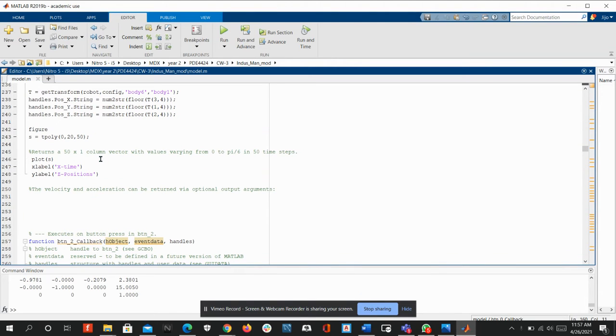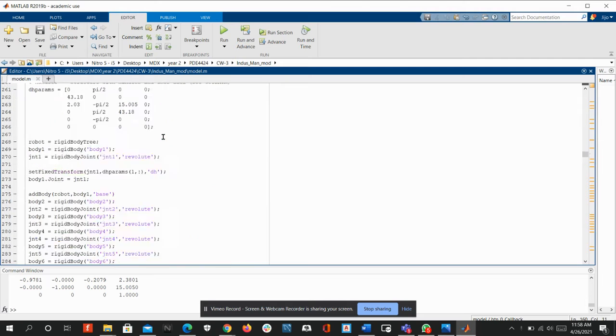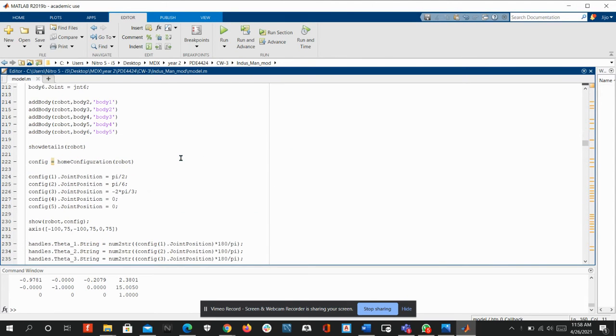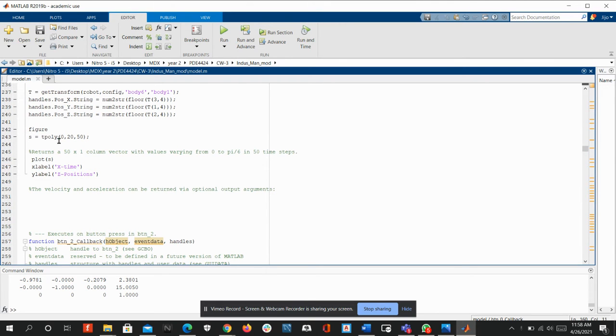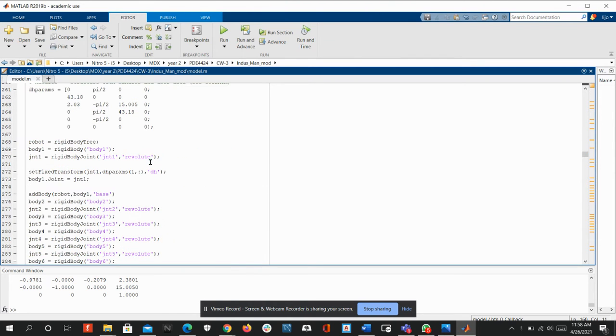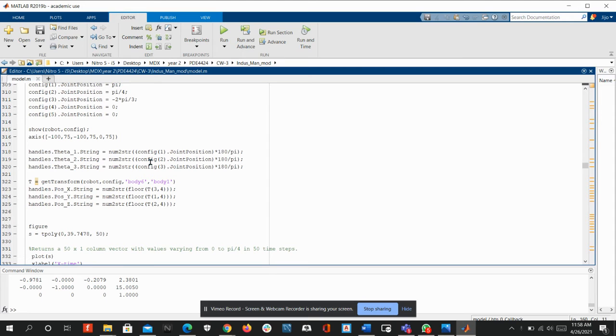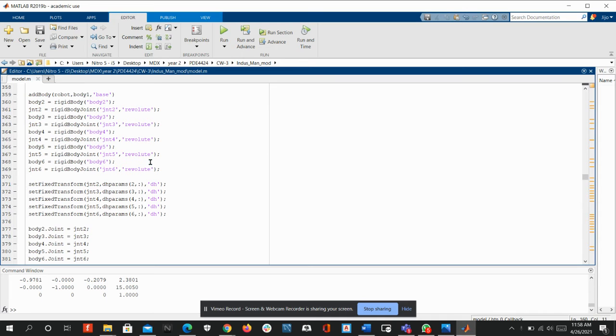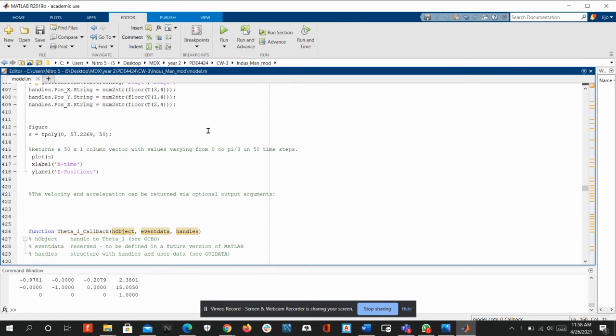This is a MATLAB generated code simulating an industrial manipulator used to lift pucks from the floor to different levels of shelf. As you can see in the code, we have used DH params and different bodies of links for the robot, and a polynomial trajectory to be used for knowing the x and z positions of the end effector in different movements of the manipulator.